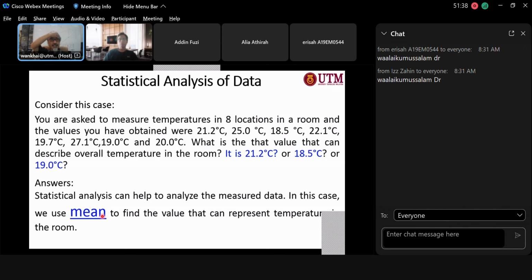Especially the fighter, they do not have the luxury of aircon, like a transport aircraft. In a fighter aircraft, normally they take the outside air to cool the pilot. So we do the profile, and sometimes we really need the actual temperature at a certain spot, especially at the face. We find that it is very critical to get the temperature around the face cool enough to make the pilot feel refreshed.